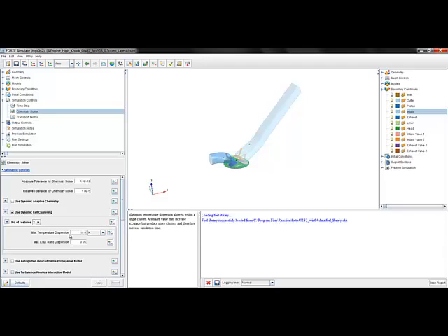However, the other unique capability is the dynamic cell clustering, and this option is always used for reacting flow simulations. This option will cluster together cells that are kinetically similar based on temperature and equivalence ratio dispersion. For example, if your simulation has 100,000 cells, the clustering may only result in 1,000 clusters to solve for chemistry. This means the chemistry problem is 100 times smaller, which dramatically reduces computational time. The ability to predict autoignition or pre-ignition lies within the ability of the detailed chemistry to predict these phenomena.